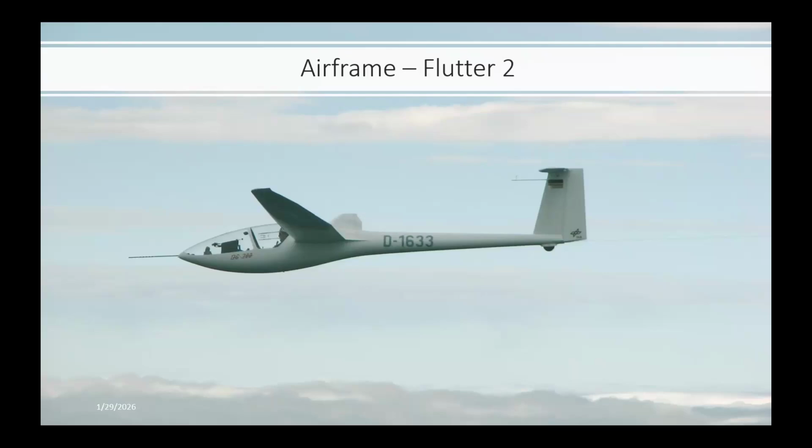The flutter oscillations stop, but only when you get down to a much lower speed than where you triggered it. And that speed where it stops is the actual flutter speed of the plane. The flutter will start when this airspeed is exceeded and the right disturbance influences the plane. So in my glider's case, it was the turbulence that I hit. When I was in smooth air, it was just fine.